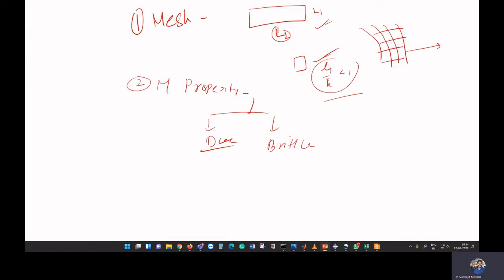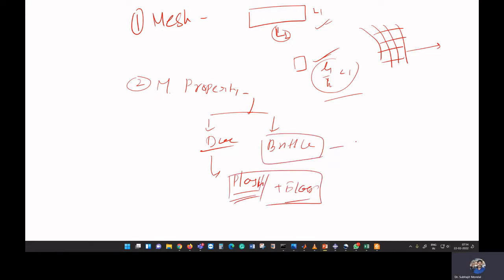If it is a ductile material, you can give plasticity data along with your elastic data. If we go for a brittle material, along with your elastic data, you have to give damage parameters. Various damage criteria are there, depending on the material type, whether it is a granular material or a fibrous material. Depending on that material, you have to give your damage parameter.